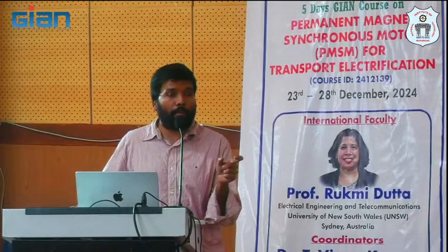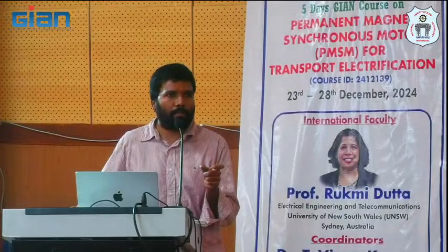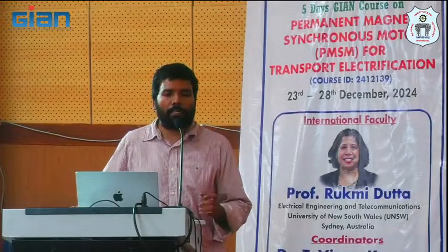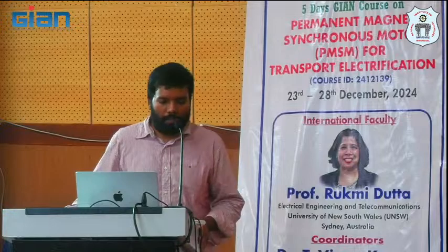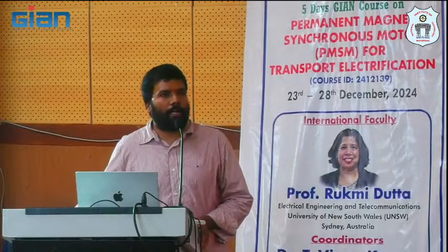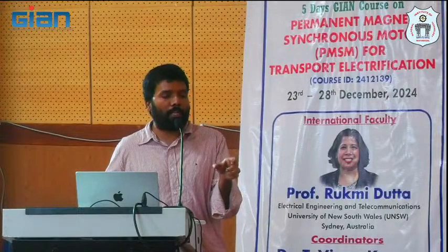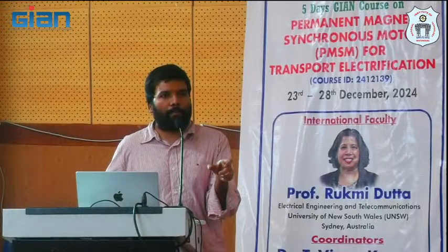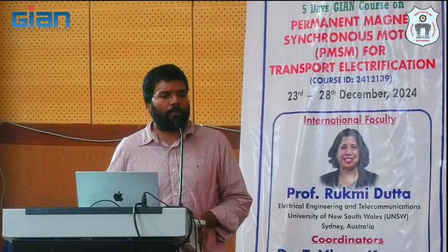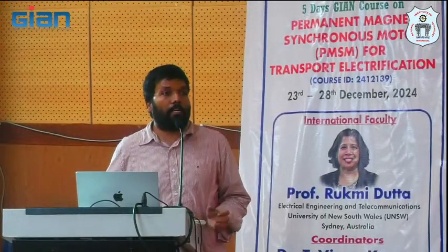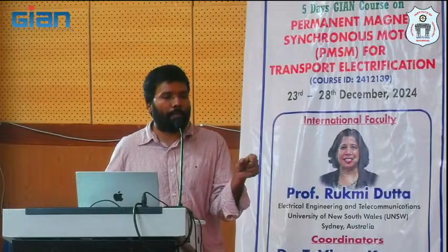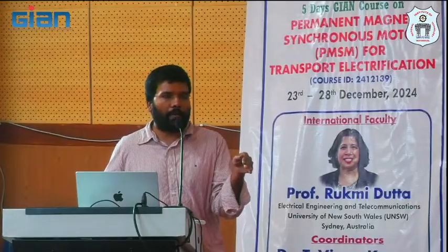If you want to regulate the current, you need to take care of the potential difference between the applied voltage and back EMF. This is a very important point, whether it is a DC machine or AC machine. Whenever you want to limit the current, the first step is you should know the strength of the back EMF. Once you know it, it is not a big deal to change the input voltage. Let us assume initially back EMF is 0.